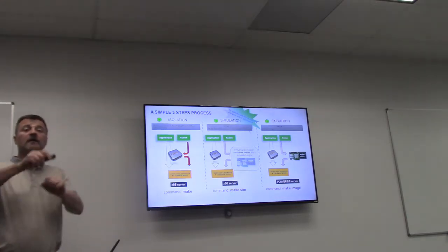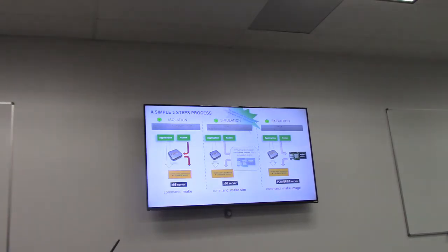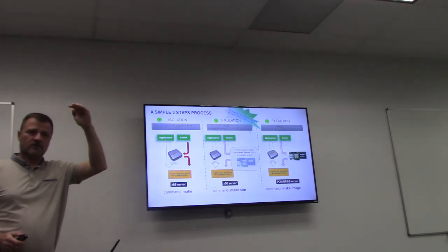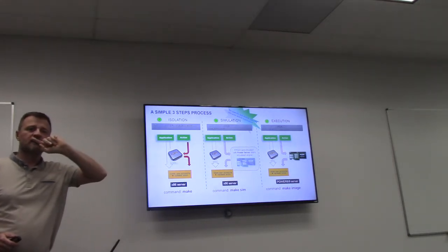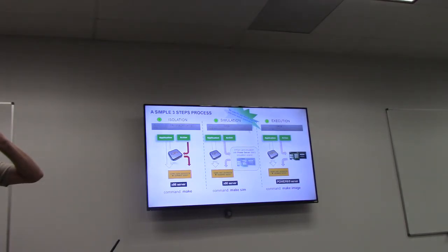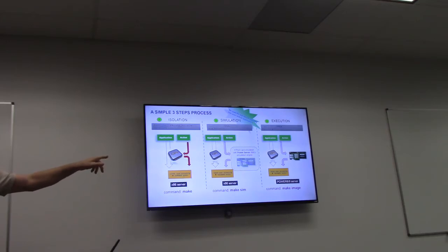Okay? So is it RTL simulation? The simulation you're mentioning is RTL simulation? Yes. High level, behavioral. Well, there is RTL simulation and there is SystemC simulation. The behavior which you're saying should be a SystemC simulation, which is quite fast. If you're saying RTL simulation, it is actually quite slow. Yes, it is very slow.